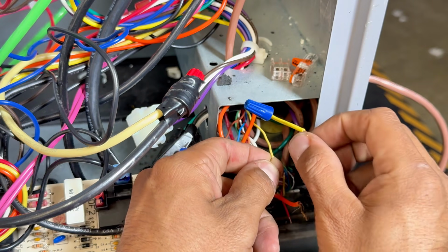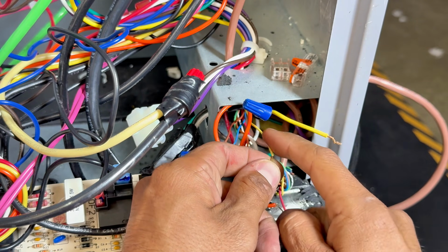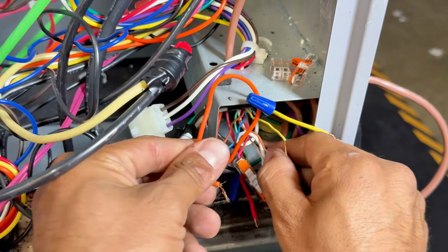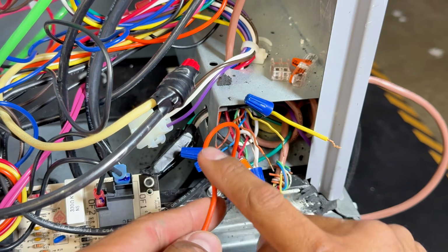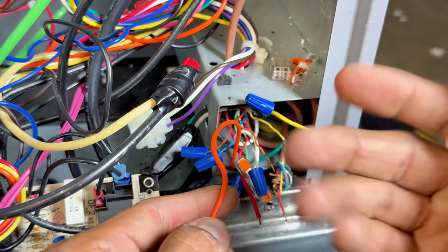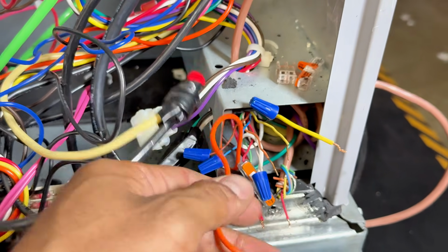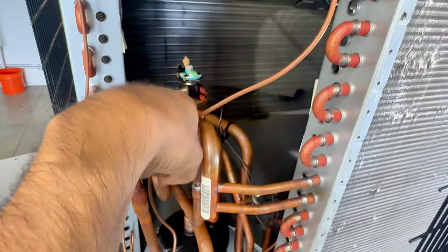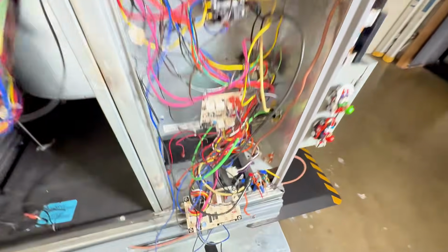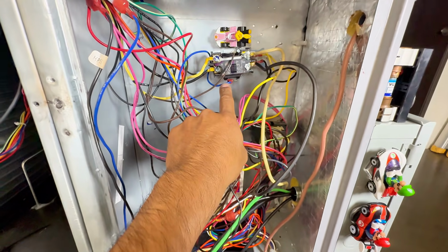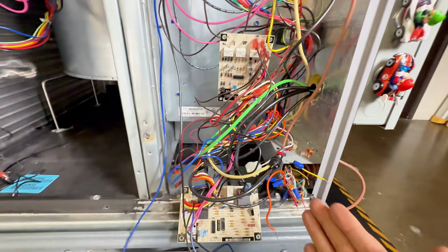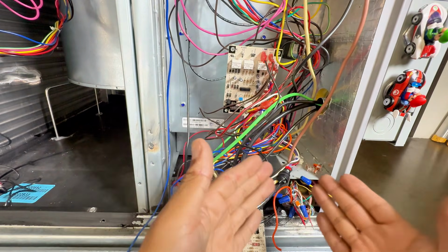The skinny red wire. And then this skinny brown wire is my common to my thermostat. And then this is for my compressor, right? The yellow one's coming from the unit. This is from my thermostat. And then my reversing valve, this is coming from the unit, and then this is coming from my thermostat. If you were to follow this orange one, that's the route we're gonna take. This orange wire essentially goes all the way to that black wire on the other side of the reversing valve. This yellow wire right here essentially goes on that side of the contactor coil. That's it. That's all we're doing. It's just the paths that the 24 volts is taking.